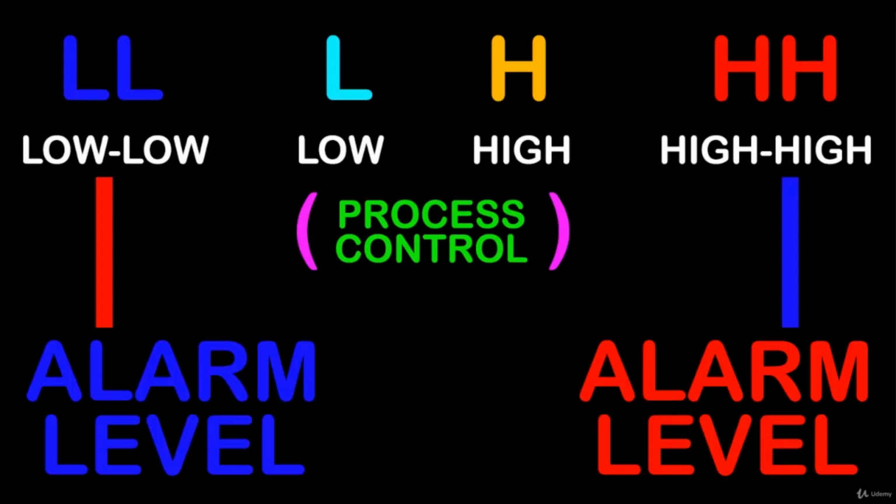We're going to figure that out because our heater is going to come on, but our temperature is going to keep going down. And somewhere below our low level, our process control range, we're going to have a low limit set that says whenever the heater gets down to 55 degrees, we need to sound an alarm and say we have a low temperature. And maybe we need to interrupt some part of our process which is dependent upon that temperature being within the control range.